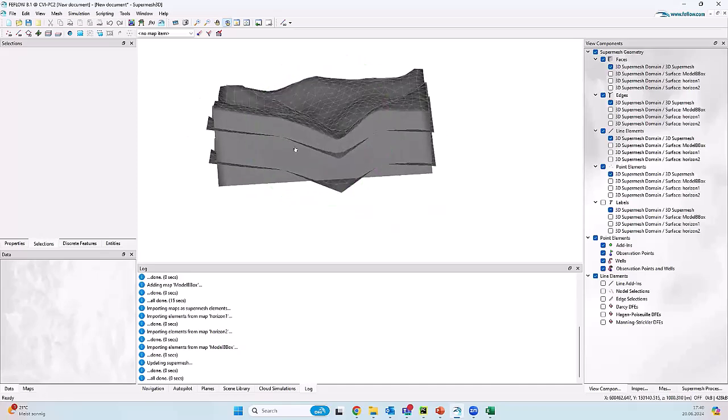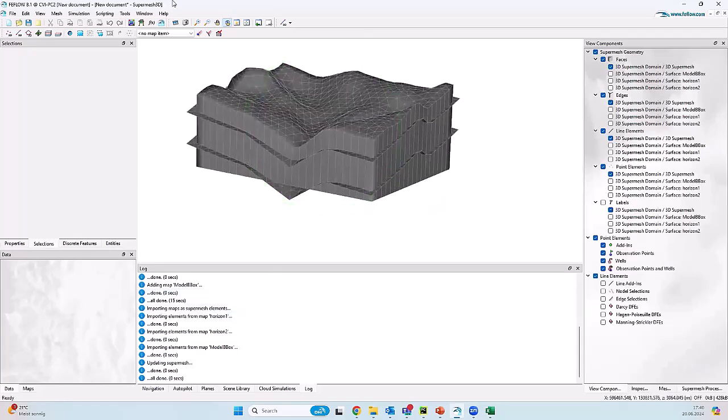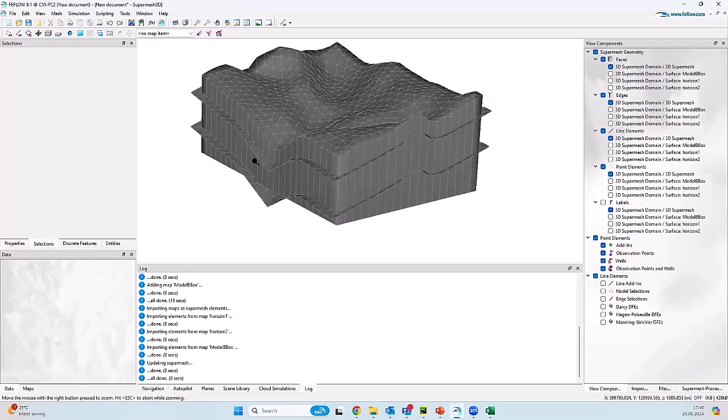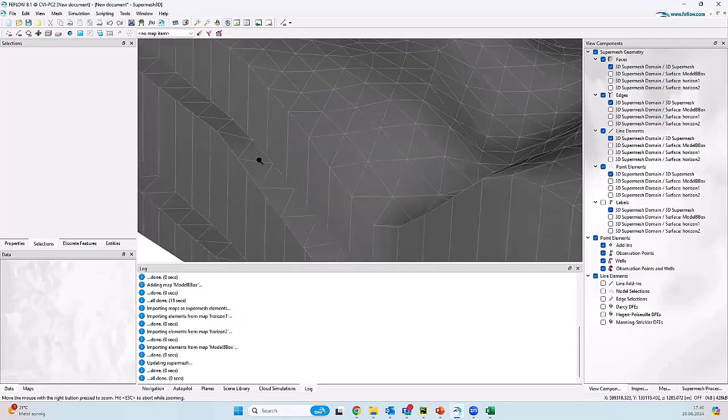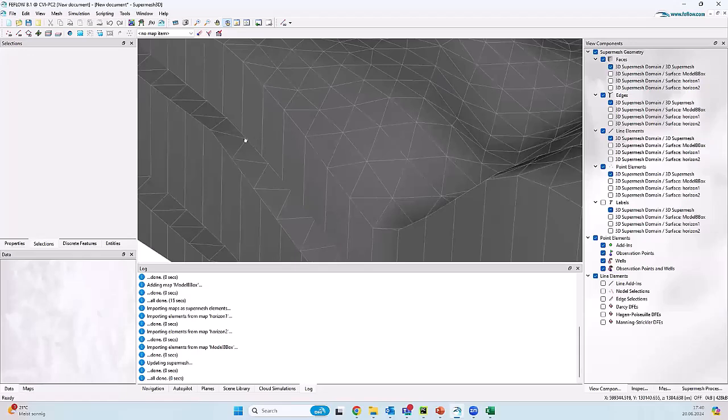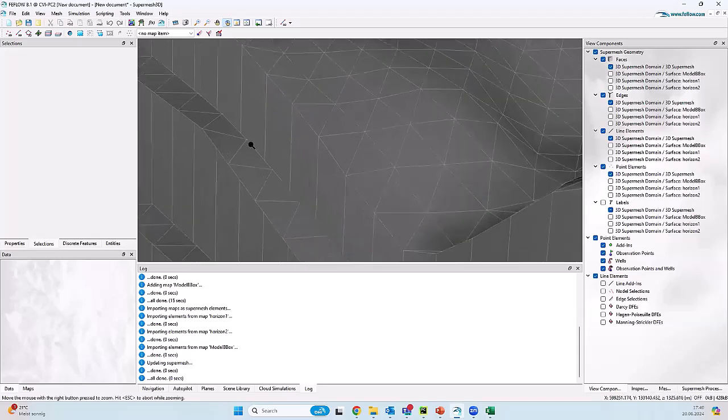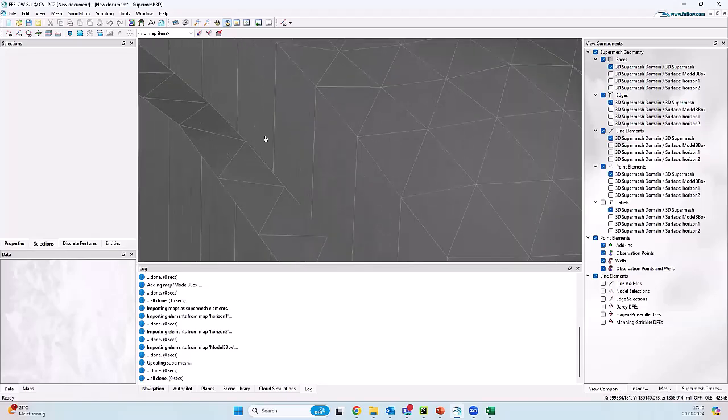And in the middle, we will introduce a tunnel, and later we'll also cut the model with a fault. Okay, so very often you will see that I'm trying to make my box smaller than the surfaces. Why? As I mentioned, the tool does identify the intersection. If you have a good overlap, or the surface is outside the box,